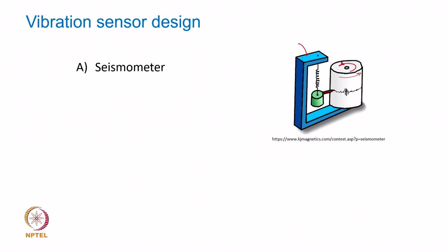Of course, instead of that you can have a pen which is vibrating like this, and the sheet which rolls like that, so that it records the seismograph. But here, for the sake of illustration, you may imagine this drum being rotated with the paper wound over it, and then the pencil or a pen attached to this mass would trace out vibration.